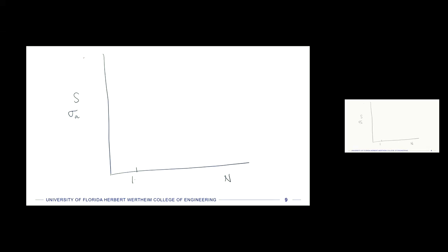We really don't have a lot of data before 10 to the third cycles, so we're really just going to start there. And then we're going to go out and assume that infinite life means 10 to the 6 cycles, 1,000,000 cycles. Okay. So we can draw what we know already, which is our endurance limit, SE prime, which is going to be half of the ultimate tensile strength. Right? We can just look that up. That starts here and goes that way. Right? So that's the first thing.